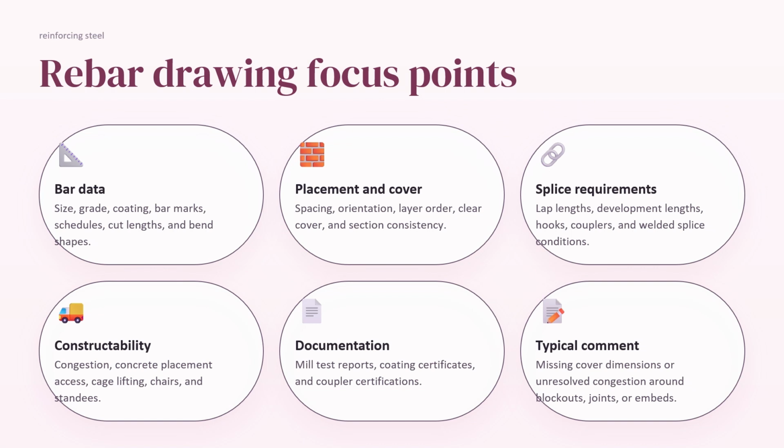And you need to check the bar mark schedule, bar placement, concrete cover, bar spacing, lap splice length, construction joint, curve reinforcement, section details, connection details, notes and references, revisions. So I will give you a simple memory trick by the end of the video so that you would understand every shop drawing.